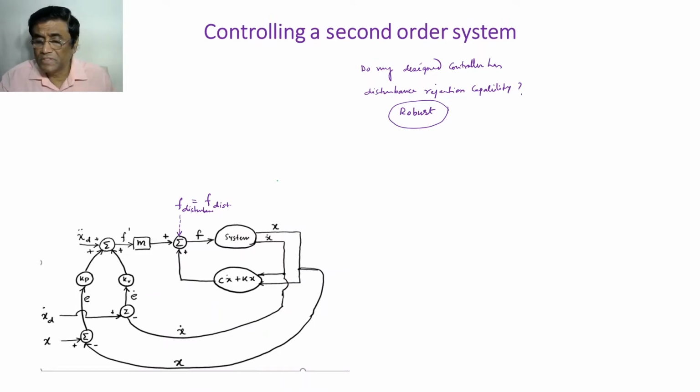And this disturbance force is very, very common in practical applications, you know, because when my robot is trying to do some job, doing some trajectory, maybe my robot model is not that great, means there are some errors, and then the robot is moving with some acceleration. So that may create unmodeled forces, which is a disturbance force.